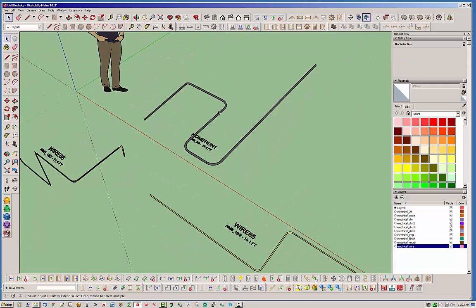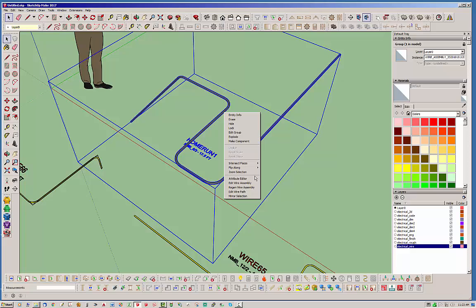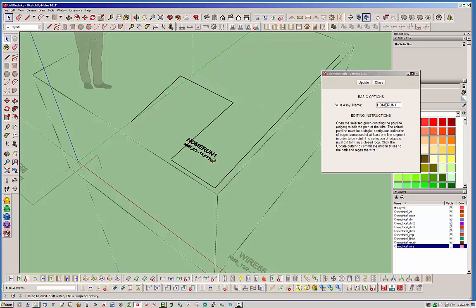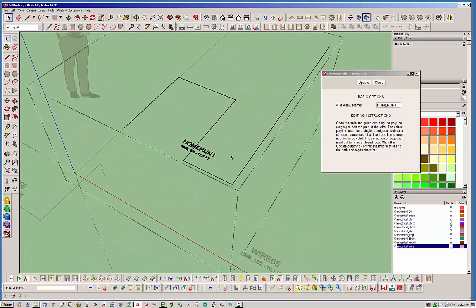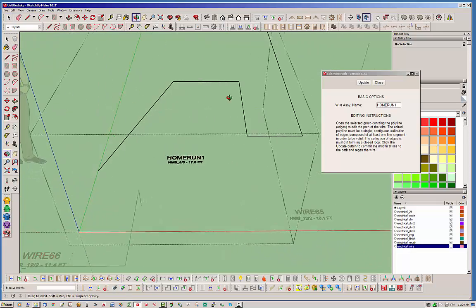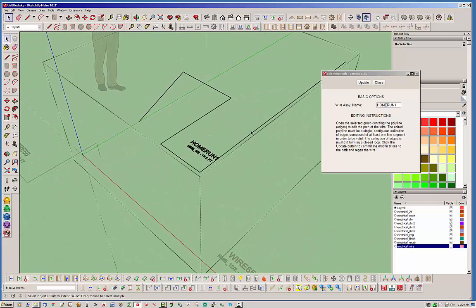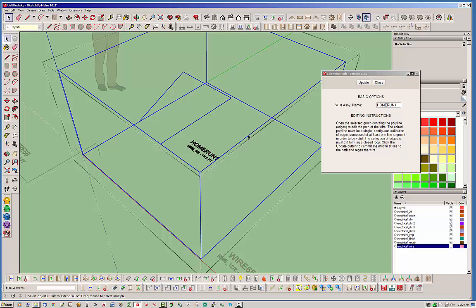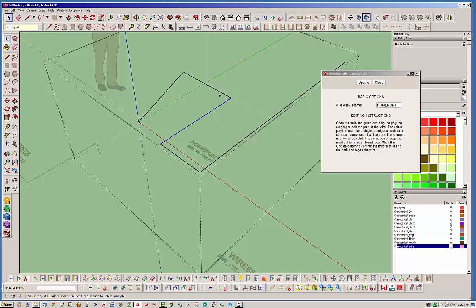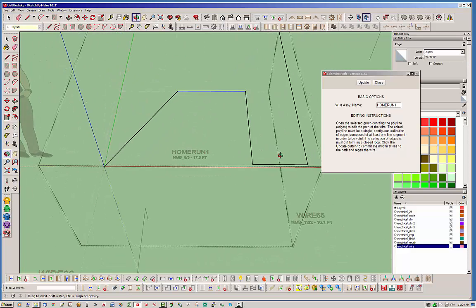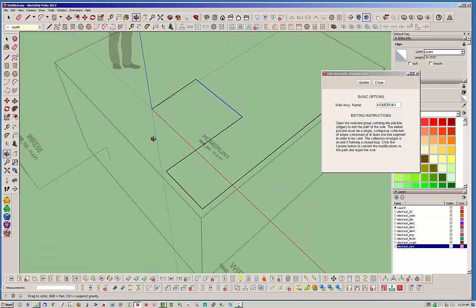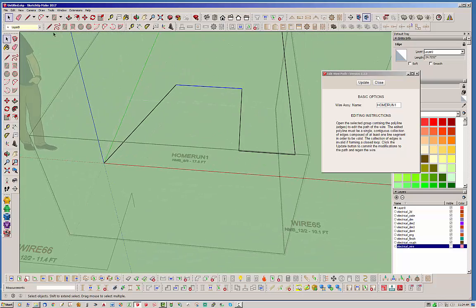And the last item that I wanted to show you guys real quick is if you do the edit wire path, what happens is that it hides the electrical wire layer, so you actually can't see that. And then it creates a temporary path from the original points. And then what you need to do is actually click into this group. And then once you're in the group, you can select these different segments, I guess. But you can add more segments. You can change the length. You can basically do whatever you need to do here.